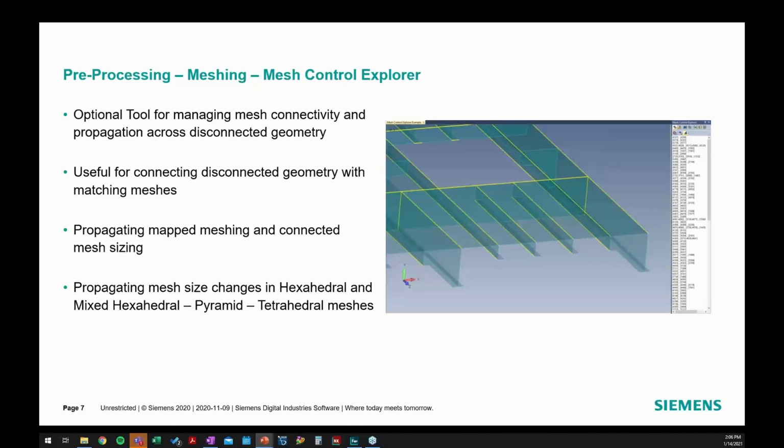And this is actually beneficial in some cases where, with the Parasolid engine, if things aren't exactly touching, then the non-manifold add command may not work properly. And yes, there is a search tolerance that you can change, but that's not really recommended. So this gives you the option that if your geometry isn't perfectly lining up, you can still handle that geometry without having to do a bunch of extending the edges of your surface to what all intersects and then having to delete off those extra edges.